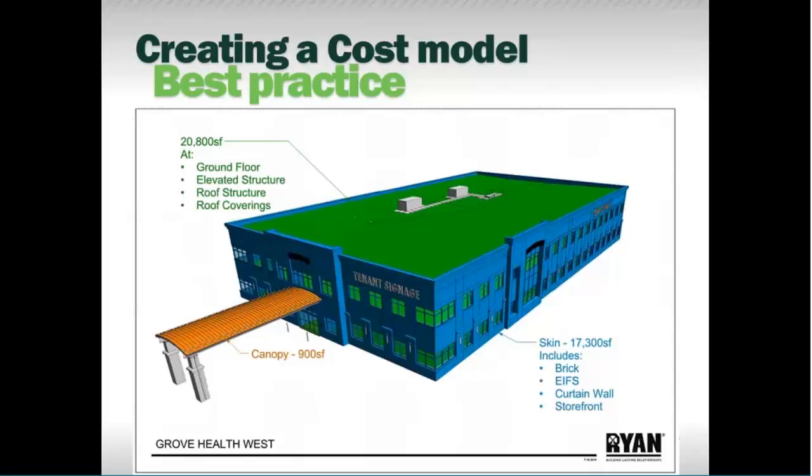And if you look at much cost information or structured cost information, what you'll see is that site, MEP, and skin are often one of your major drivers. And so a square building is the most efficient. The longer and skinnier you get, the more skin you have for the square footage. Most architects don't like designing pure squares, so they're usually at least some sort of rectangle, and then on up from there.